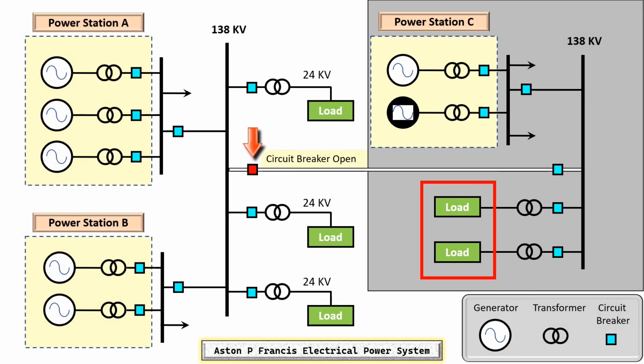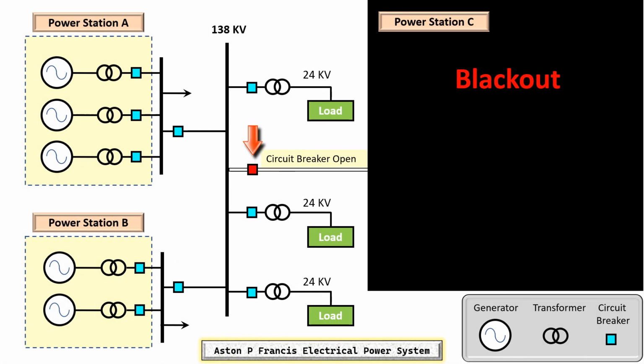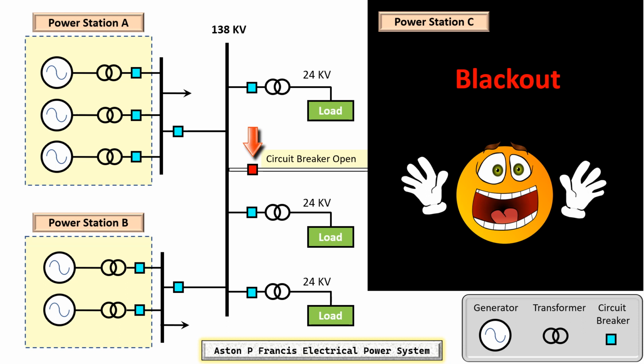In this scenario on the right, the load has exceeded what those two generators on top can supply. So this generator goes offline. When that happens, other generators can trip. In this scenario there is a total blackout on the right, because there is a grid separation and the system controller or dispatcher is not aware.